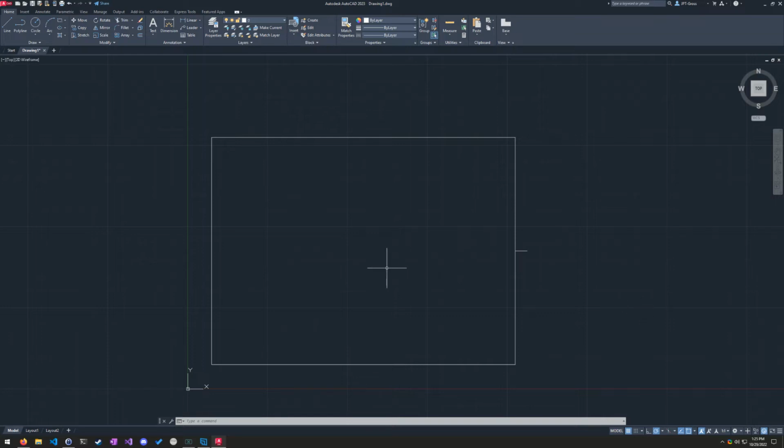I'm going to go ahead and repeat that all around the rectangle. Now I could press L, enter to get back into the line tool, but instead, to save a little bit of time, I'm just going to press the enter key. If you're not in a tool and you press the enter key, it brings up the last tool that you used, so that you can repeatedly use the same tool over and over again if you have to, like we have to here. So I'm just going to press the enter key.